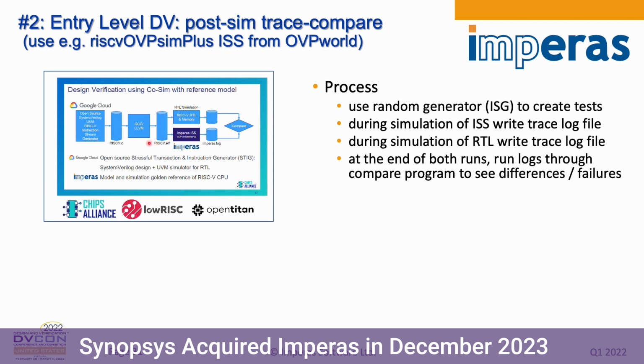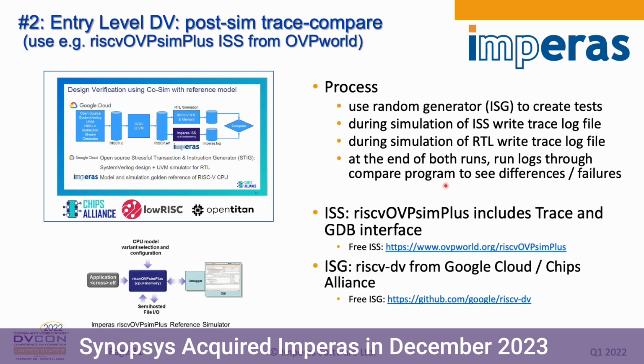And then you run that program on your RTL, and you run it on a reference, and you do it by tracing all the instructions coming out. So it's a log file, not just of a few printf statements, but actually of instruction by instruction and register by register. You dump out a trace, and then you write a program to compare these traces and to try and keep them in sync. And at the end of the run, you compare them and see how that works.